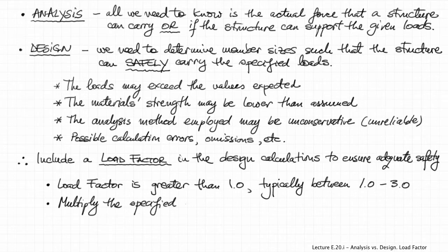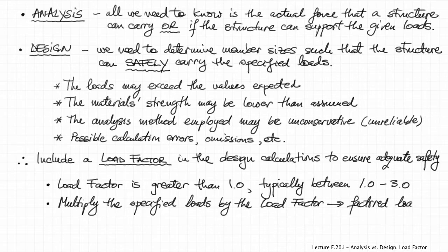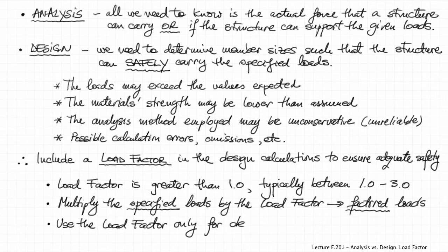The load factor will be multiplied, will increase the specified loads, and this would lead to what is called factored loads. So the originally given loads are the specified loads. The loads multiplied by the load factor are the factored loads. And the factored loads are the ones that are being used for design, because we want the design, again, to lead to a structure that can safely carry the loads.